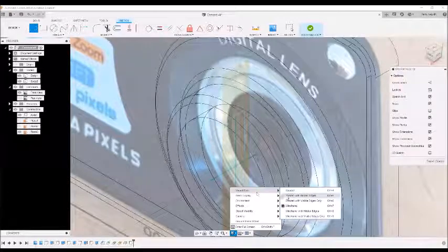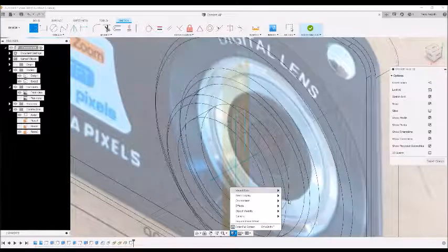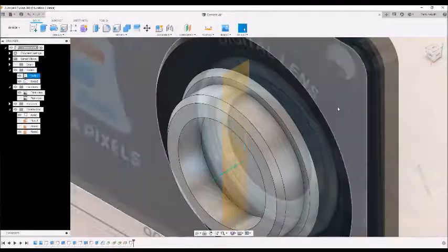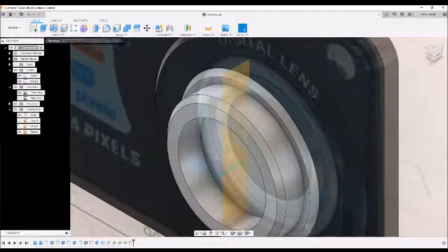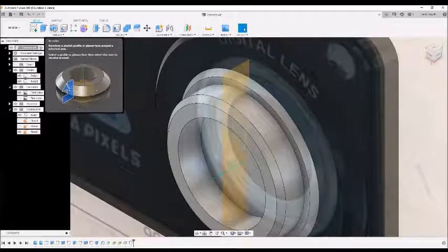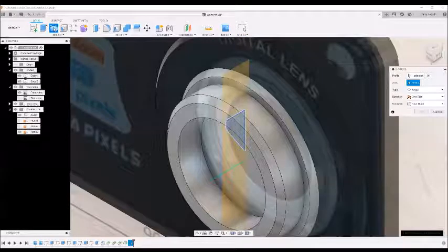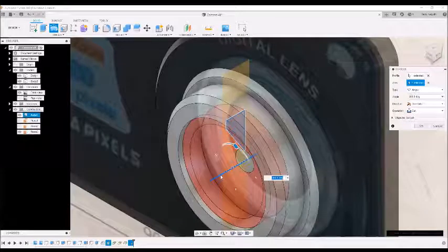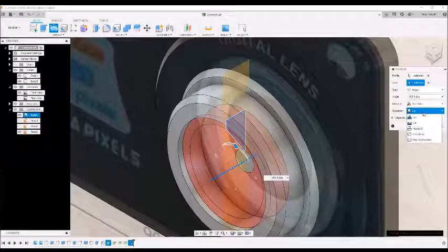So the first thing I'm going to do is switch the view back to solid colour. It's just a little bit easier to see what's going on with 3D modelling. Once I've finished the sketch, I'm going to go to the top toolbar and click on the revolve tool in object. I can now highlight the shape that I've just drawn. And the second thing I need to select is the axes that I selected before, and you can see the preview of the shape I've drawn start to appear.